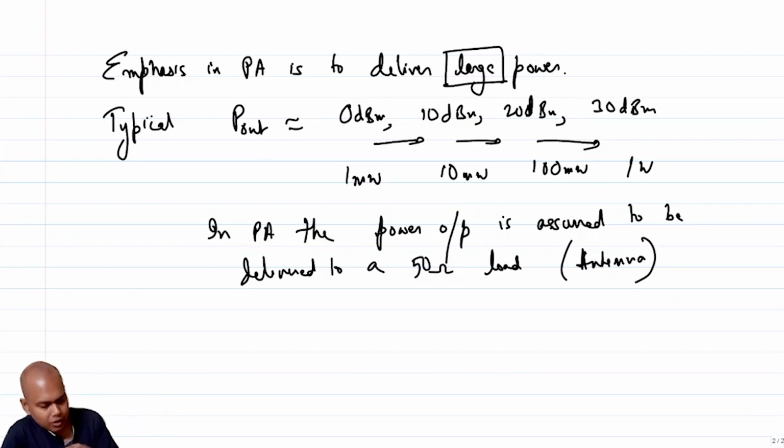But assuming all of these are true, at least in this course, we'll go ahead by assuming that the antenna is 50 ohm, right? Because the principles of design still hold, just that you'll have to calibrate for non-50 ohm resistances or impedances once you design using a 50 ohm assumption, right? So that's another assumption we'll keep in mind.